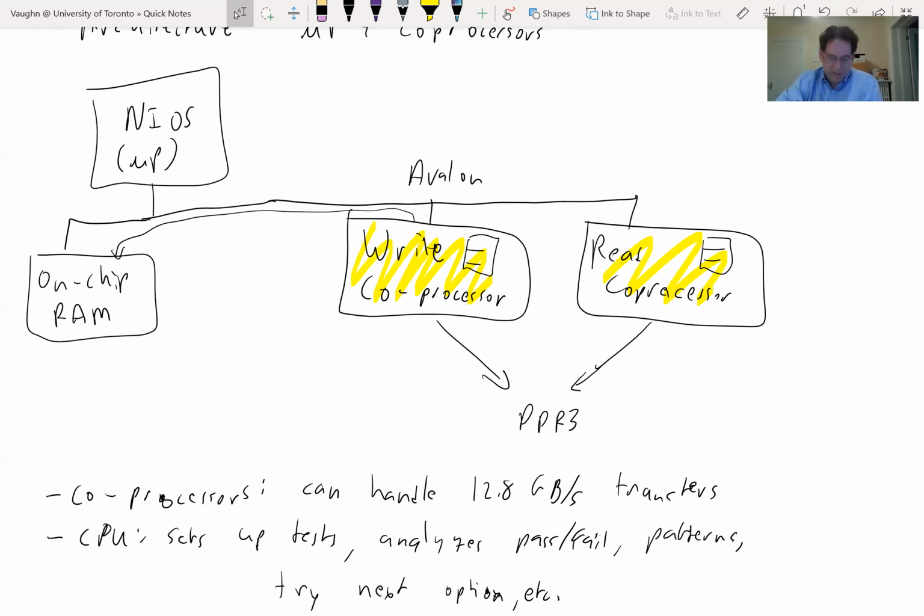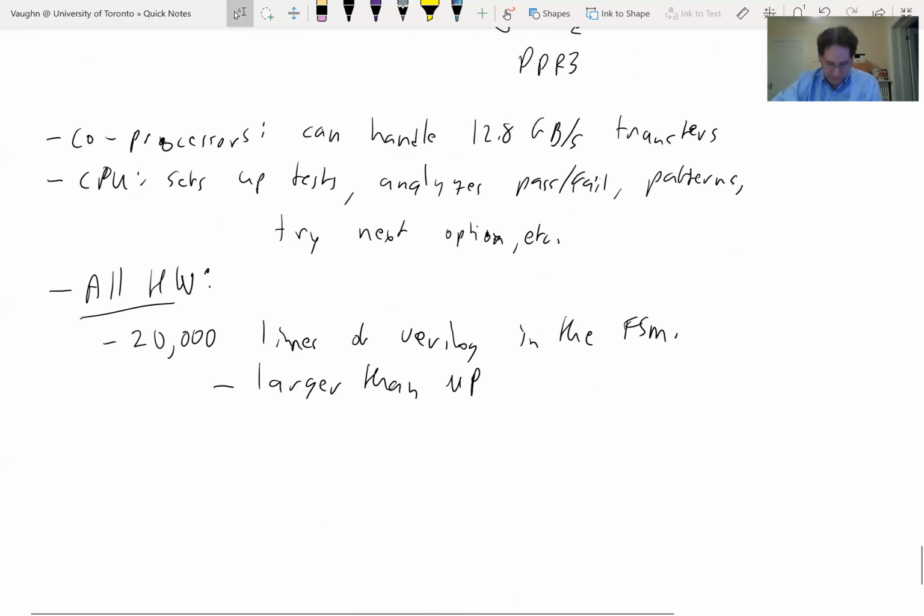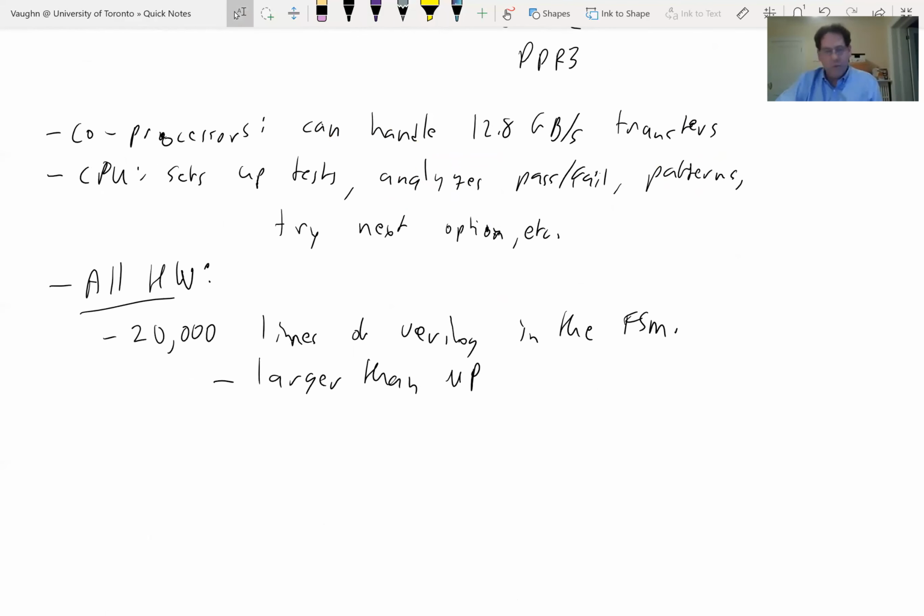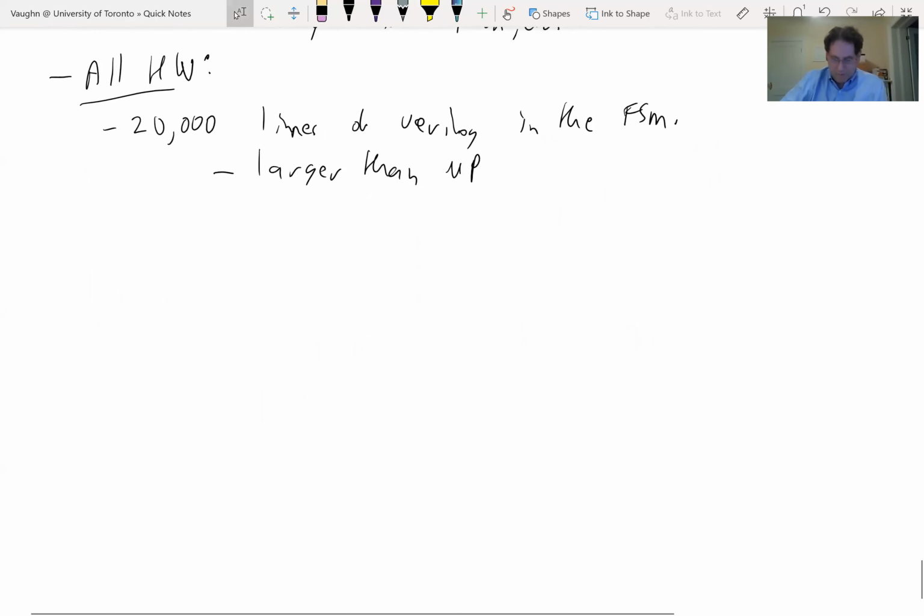And this was basically, you can choose how high a performance of a soft processor you want. We could use essentially the lowest performance version because it's just controlling these coprocessors. So this was a win in a lot of ways. It basically made the developers far more productive and agile, and the control was so complicated that this is where a microprocessor is good. When control gets really complicated, they're actually very efficient because they store that control in just instruction words.